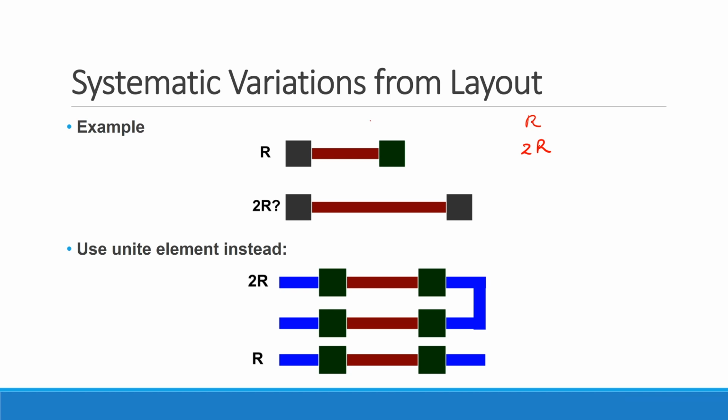The contact resistance is fixed, right? So if I actually look at this thing, what I really get is RC, meaning the contact resistance, plus the R of the physical resistor that I actually intended to build, plus another contact resistance here, right? Well, if I do exactly what's drawn on the thing on the bottom, I'll still get a contact resistance. Now maybe I really will get double the resistance in the center. But again, I've got another fixed contact resistance over here.